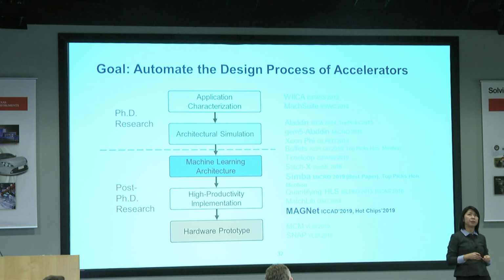Yeah, so we measured results for AlexNet and also DriveNet, which is more a self-driving network. AlexNet and ResNet, well, of course, there's a large design space with different tiling, but they are pretty similar in terms of the scale of the network, where you need to think about not only network on chip, but also network on package communication. The particular DriveNet that we use is pretty small, so most of the layers can fit into a single chiplet. So you observe less of this kind of strong scaling effect, and we're mostly experimenting with weak scaling there.